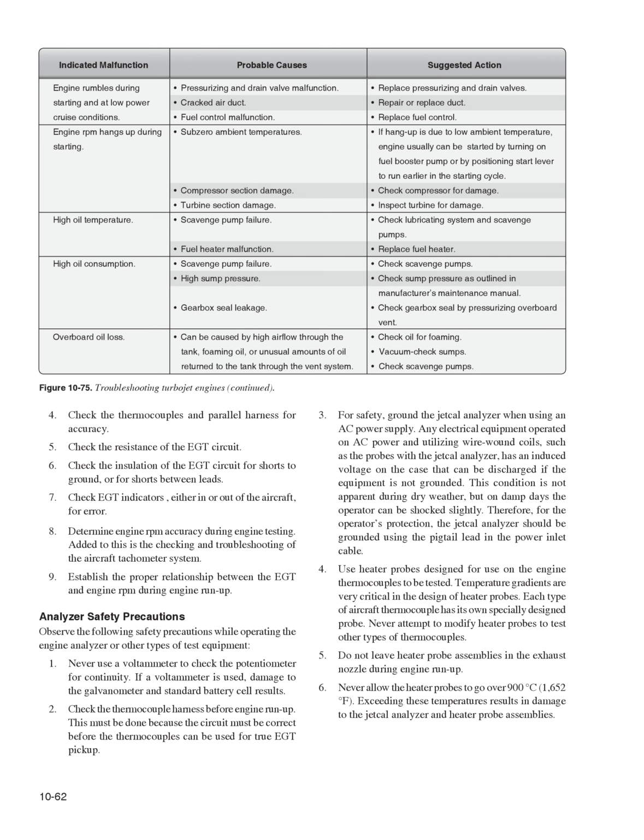3. For safety, ground the JetCal analyzer when using an AC power supply. Any electrical equipment operated on AC power and utilizing wire wound coils, such as the probes with the JetCal analyzer, has an induced voltage on the case that can be discharged if the equipment is not grounded. This condition is not apparent during dry weather, but on damp days the operator can be shocked slightly. Therefore, for the operator's protection, the JetCal analyzer should be grounded using the pigtail lead and the power inlet cable.